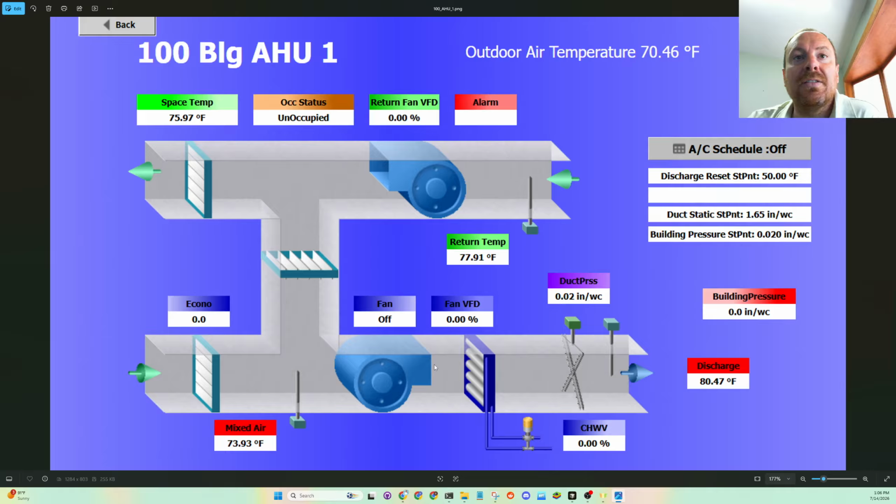What the fan does is, this is a variable volume fan on a VFD drive. I have no idea how big it is, how much horsepower or the volume that it is designed to push, but the control PID behind the scenes would output fan speed, maintaining the set point of 1.56 inches, with no hunting or anything like that, but there's no reset of it either.